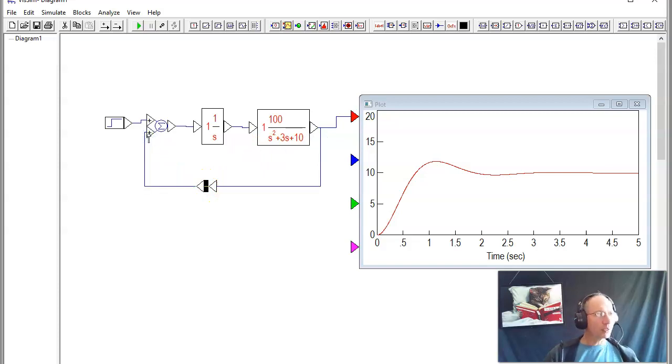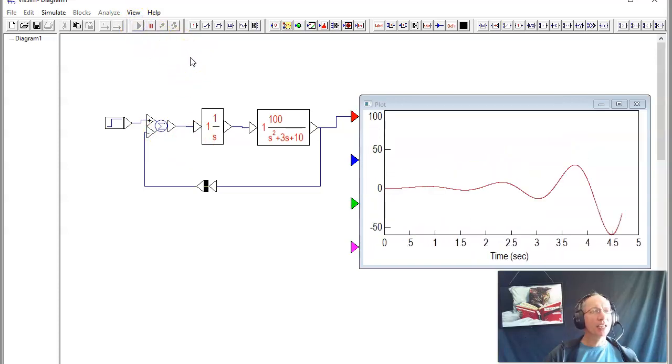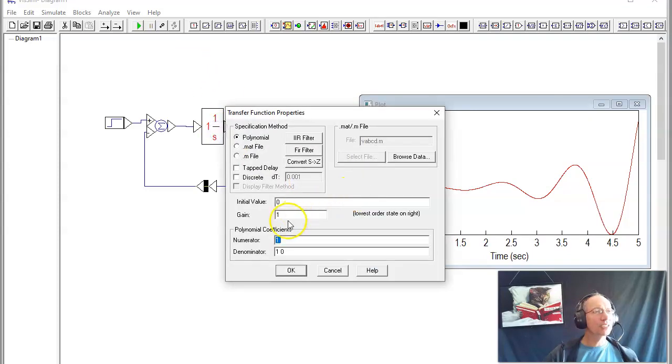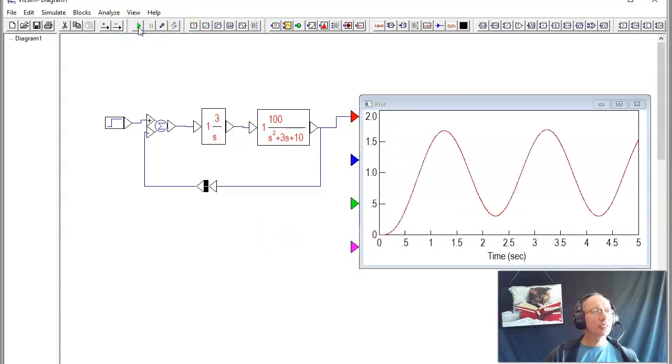And this is one that's actually not well documented. I do Control, right click, I can change that sign. Here I'm using negative feedback. I can sit there and see what happens. Here's my negative feedback, and I just went unstable. Again, change the gain. Let's try gain of 0.3. And I've got an oscillator. Some ways to simulate it.